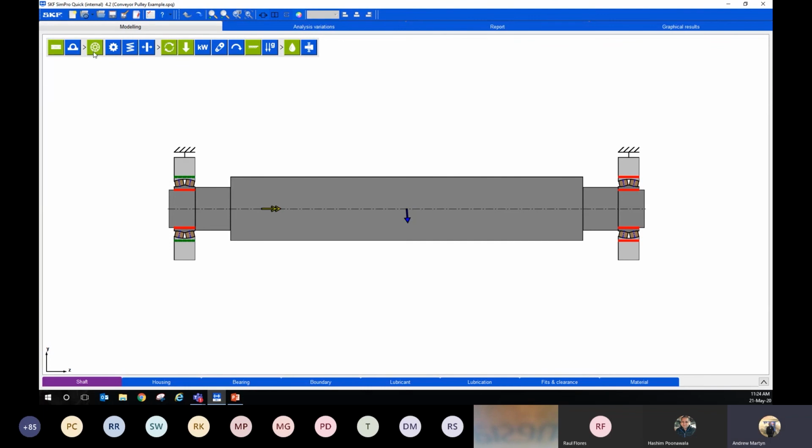So this is how we put bearings in. The functionality of this also includes gears. You can add springs to bearings, which is handy when you've got minimum load concerns, or you're using things like angular contact bearings or thrust bearings or taper bearings. The same thing with these spacers that you can put in, you can do different setups. What you can actually do is vary the spacer or the axial displacement on a thrust bearing, a taper roller bearing, or an angular contact bearing, and see the effect that doing that will have on your results.